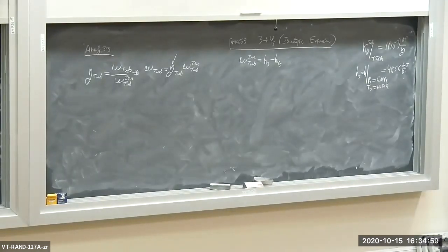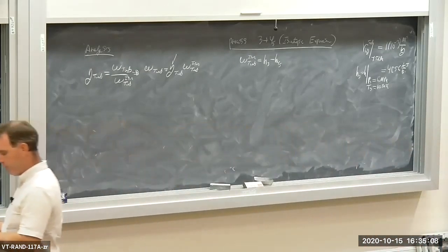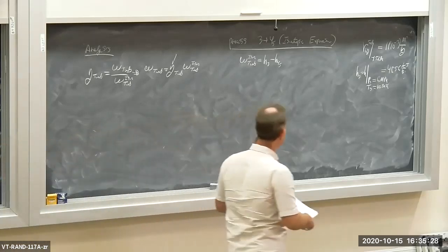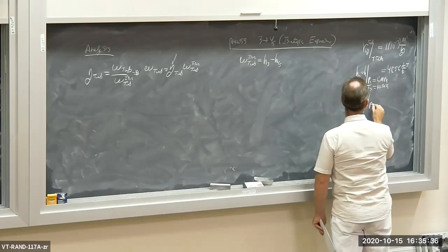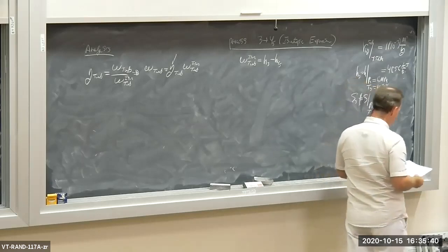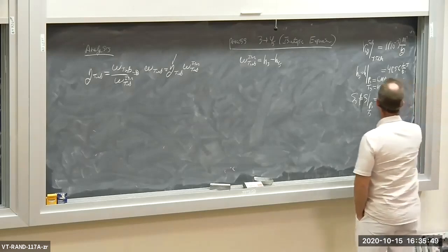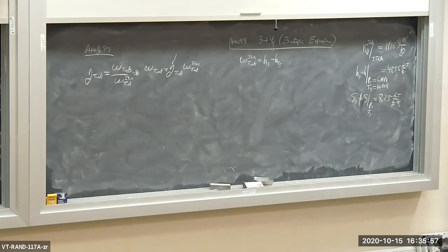By the way, the specific entropy at state 3, let's see if I can find it here. Oh, did I write it down? Yes, the specific entropy at state 3 is 8.25. So S3 is S evaluated at P3 and T3, which is equal to 8.25 kilojoules per kilogram degree Kelvin. Okay, that might be important because we have an isentropic process going on here.